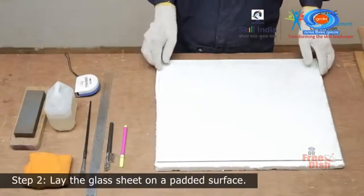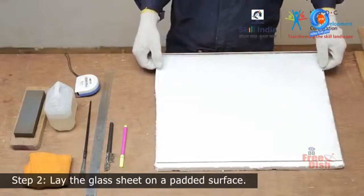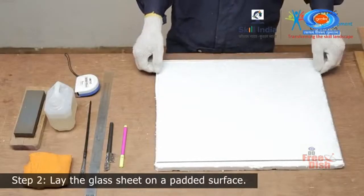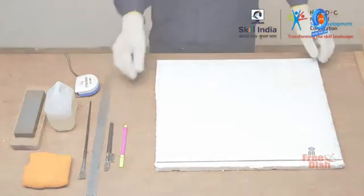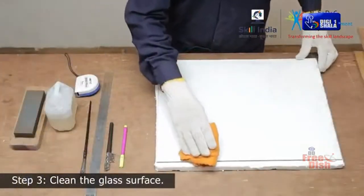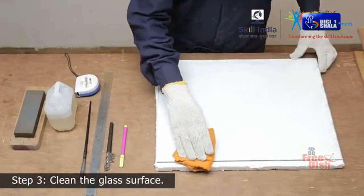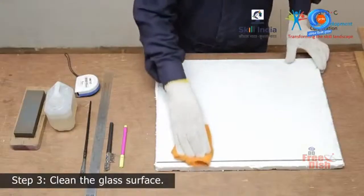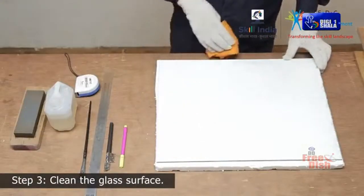Step 2. Lay the glass sheet on a padded surface, preferably one that is slightly soft and won't scratch your glass. Soft cardboard is an ideal choice. Step 3. Clean the glass surface along where you plan to cut. Any grime on the glass can ruin your score. Run a cloth along the surface of the glass.